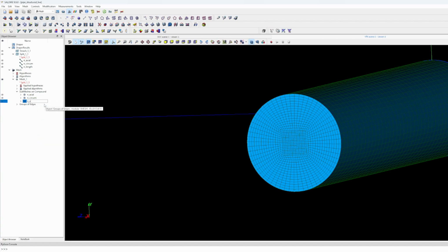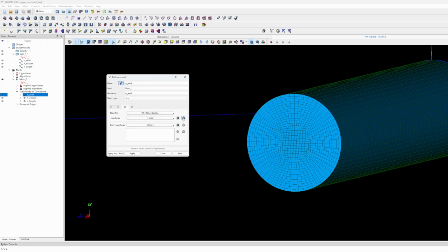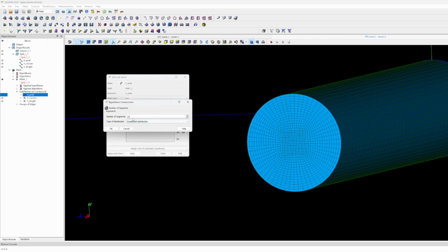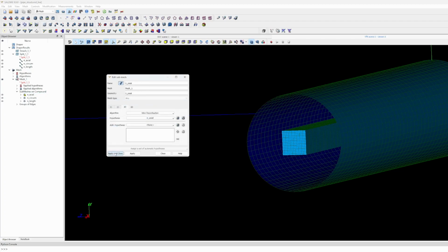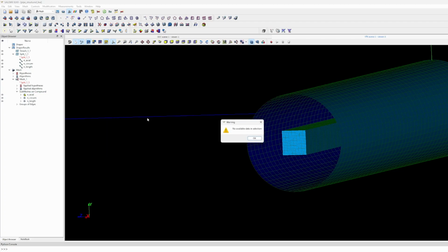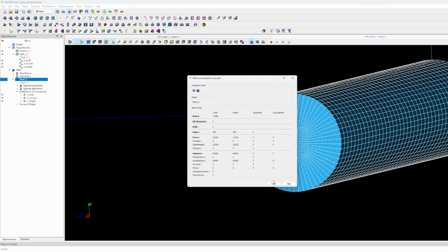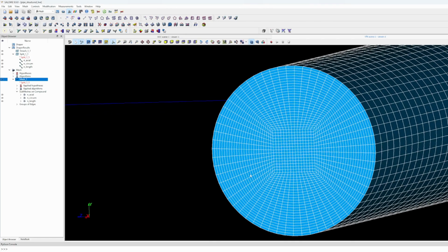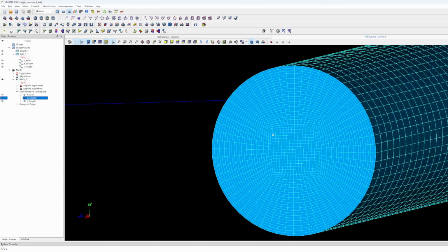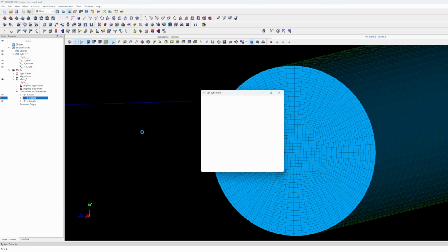And okay, you can, for example, increase the number of cells in axial direction from 15 to like 25. Okay, let's do 25. Click. Oops. Okay. Remesh. Now you can see here it's much finer, and you can also play around with the circumferential numbers.